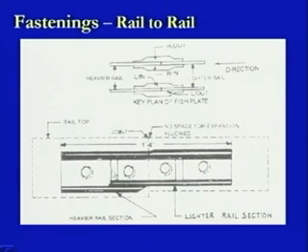So, this line is the end of one fish plate, and this line shows the end of the other fish plate which is coming from this direction. In that sense, when there is overlapping of the area, what we find is that there is additional thickening at the joint section like this. So, this is additional thickness at this level, additional thickness at this level, and this is the normal thickness of a fish plate on this side and normal thickness of a fish plate on the other side.